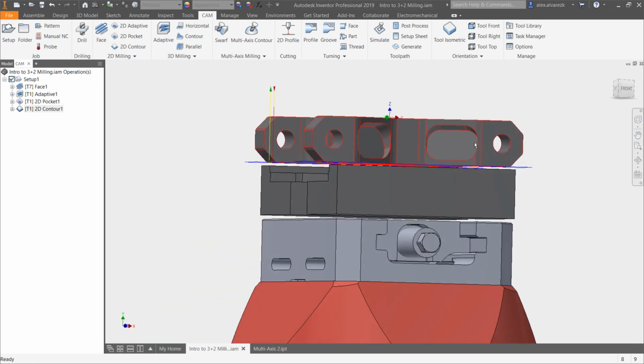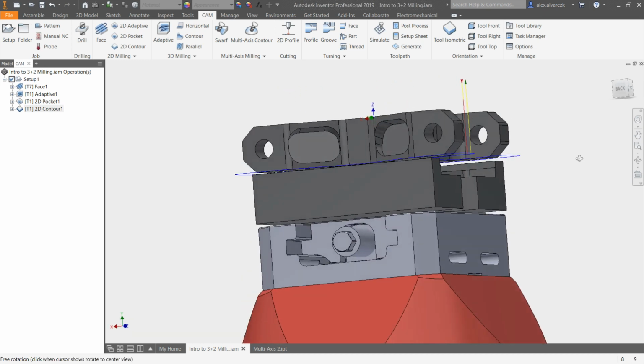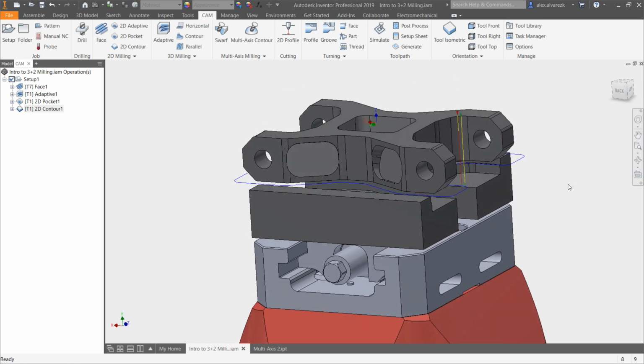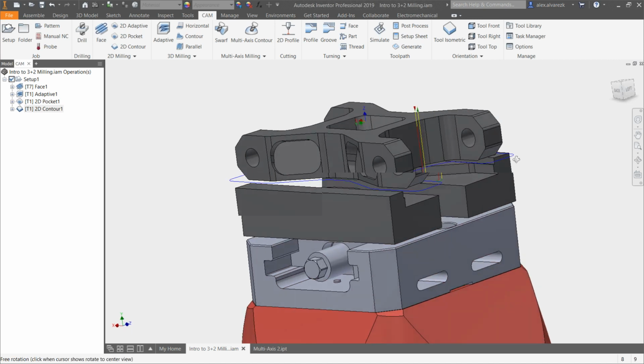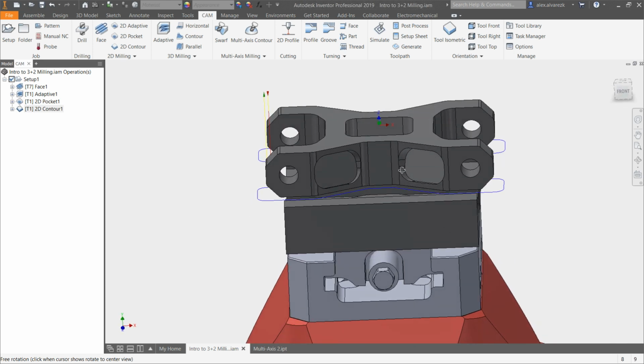And then, the fixture for this other pocket over here, then you have to flip it. And then you have a few more pockets here. So you would at least have 3+, 4+ different work setups in order to get this part done. Again, let's go ahead and take a look at how many setups it would take to essentially create this part here, right?